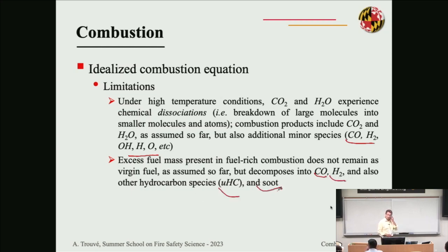So typically this global combustion model actually works pretty well for well-ventilated, overventilated conditions, and starts to lose accuracy when you go to the underventilated regime. So this model is actually very good for qualitative analysis, but lacks quantitative accuracy, especially in the underventilated combustion conditions.